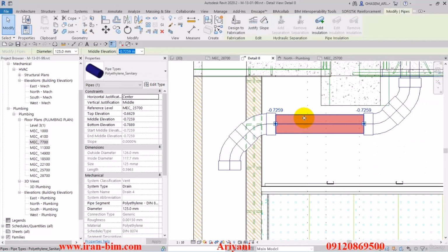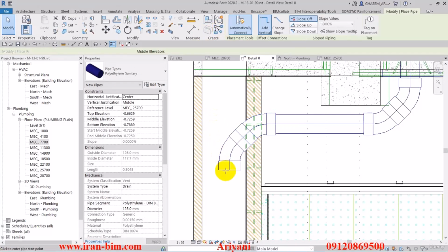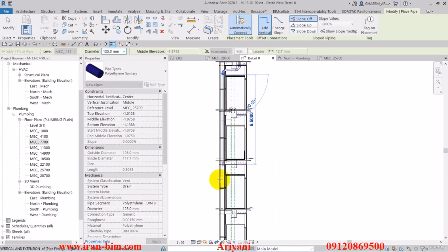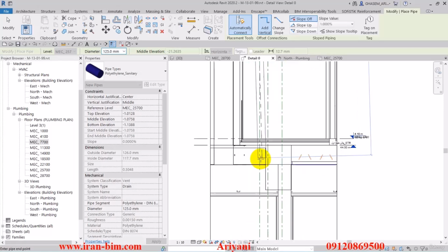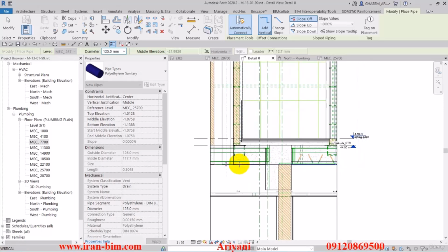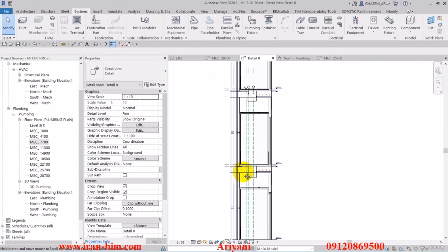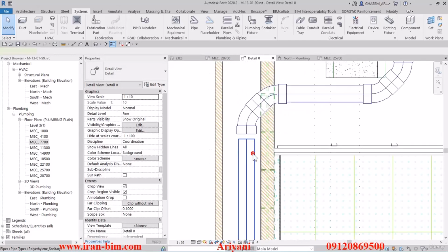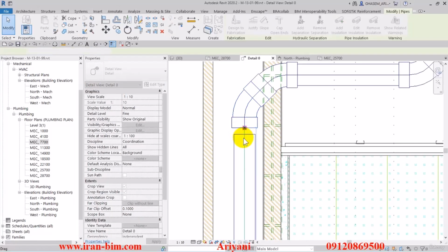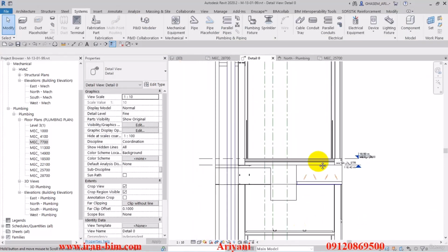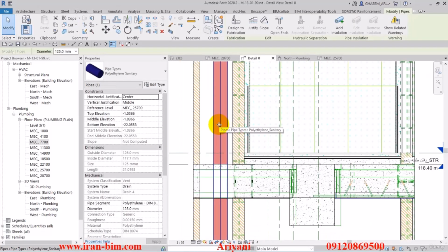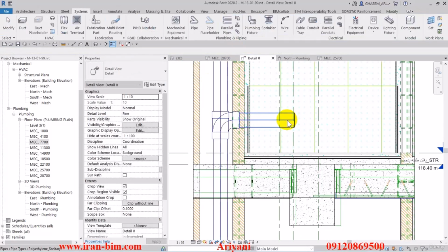So I'll select the pipe itself once again, then we'll start drawing a new pipe all the way down through the levels here to this level that says 4.1. We'll specify the directions later on. Alright, after that, I'll connect the pipe to the fitting as well. Now after that, we can go over to the level 18 itself. Here I'll create the vertical piping system and then delete the piping piece of it and keep the fitting.